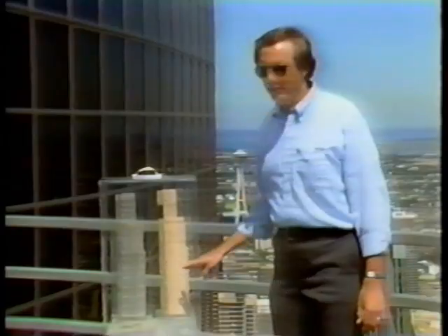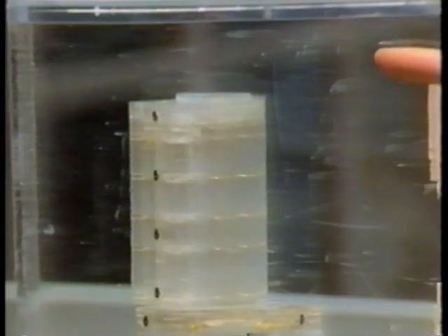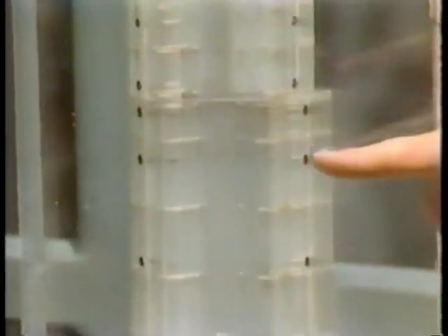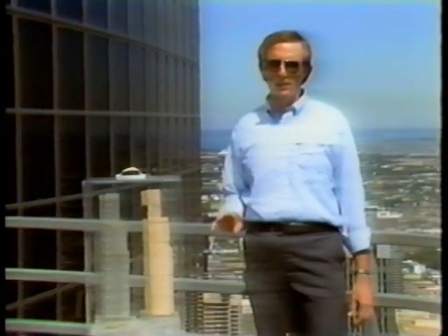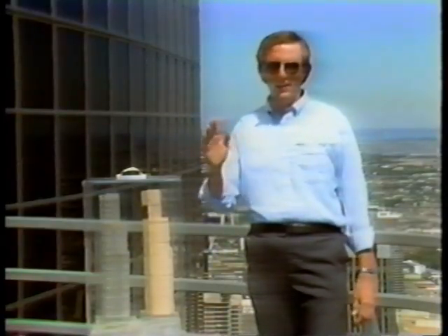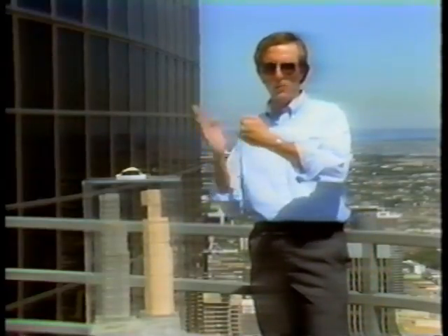These two models were used in the actual wind tunnel testing at the University of Western Ontario in the design phase of Columbia Center. The model on the left is a static pressure model. It's solid plastic, and it does not flex much when the winds in the wind tunnel affect it. Surprising thing about Columbia Center is that it does not sway in the direction of the wind primarily. The most significant component of its vibration is transverse to the wind.